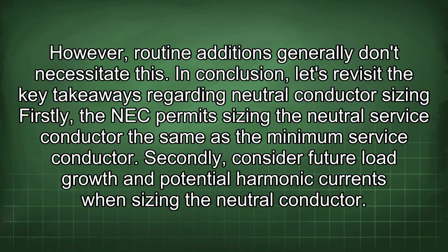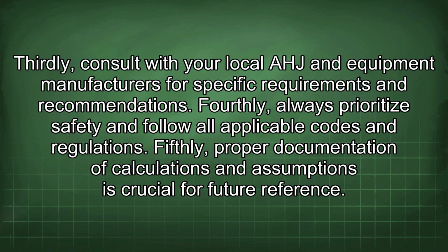In conclusion, let's revisit the key takeaways regarding neutral conductor sizing. Firstly, the NEC permits sizing the neutral service conductor the same as the minimum service conductor. Secondly, consider future load growth and potential harmonic currents when sizing the neutral conductor. Thirdly, consult with your local AHJ and equipment manufacturers for specific requirements and recommendations.